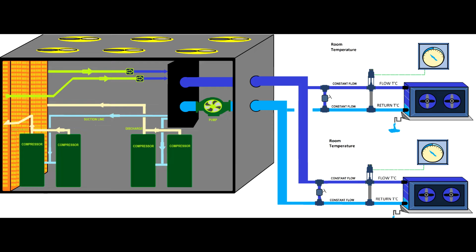Now, if the thermostat has a demand and instructs the actuator to turn on the two-way valve, then the two-way valve will allow the very cold cooling agent, which is a glycol water, to pass by to the heat exchanger. And you see now the fans moving on these fan coil units. If the fan moves, it means they are circulating air through the heat exchanger.